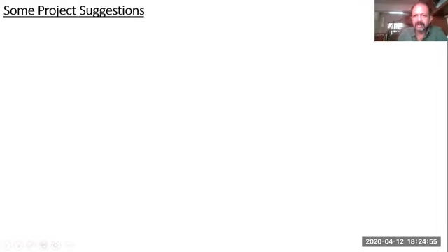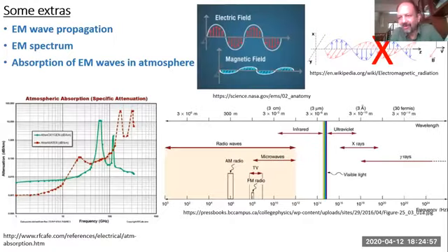So that is what I meant. Always keep asking questions. Why 77? Why not 60? Why not 50? And that's the reason. See, this is 10, 20, 30, 40, 50, 60. If you end up using 60 gigahertz, you're using a very, very bad frequency because the attenuation because of atmospheric oxygen is the highest over there.